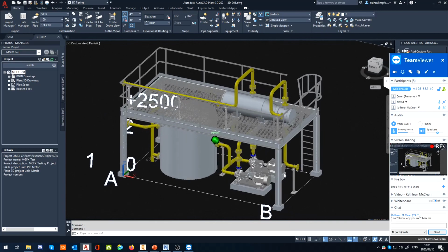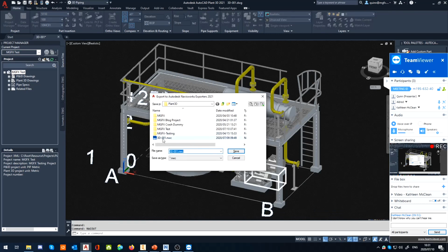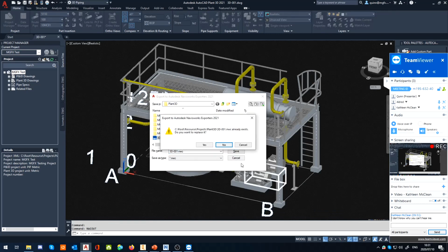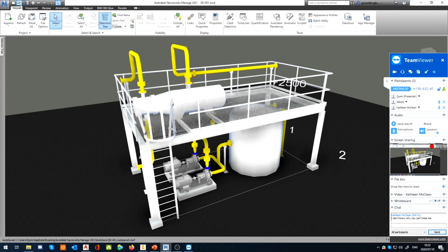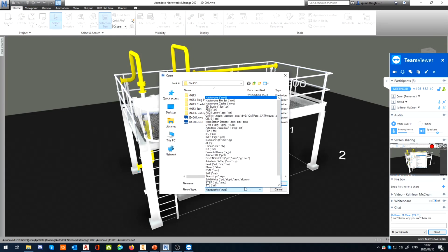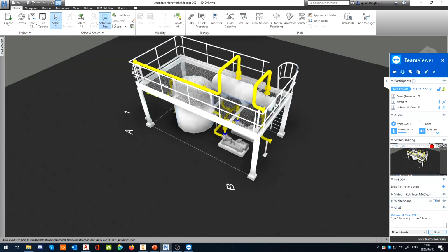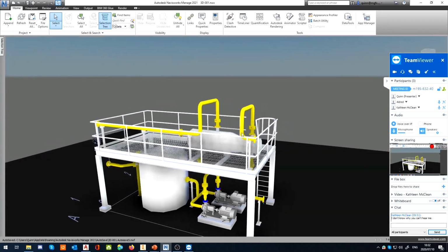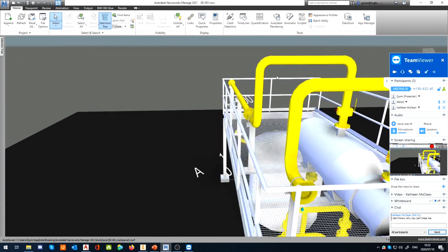and we would type out NWC out, enter, and then I'm just going to overwrite my prior one and save it. Yes. We want to keep this model open and then go into our plant. I'm going to save what I was doing here. Open, change it to my NWC, and now it's open correctly without missing any pieces like elbows or any strange bits and pieces.